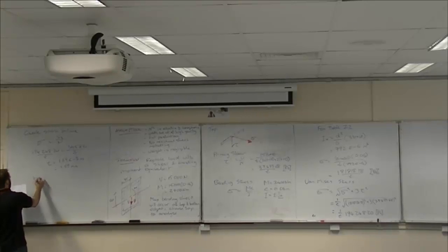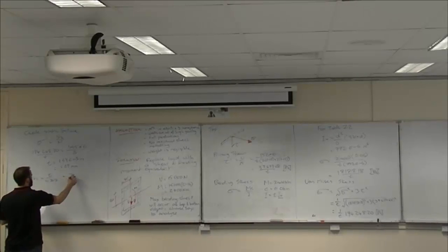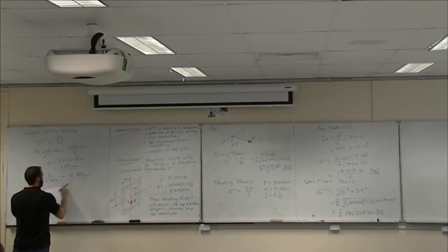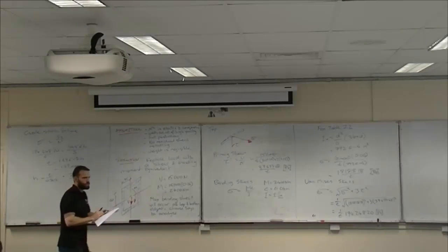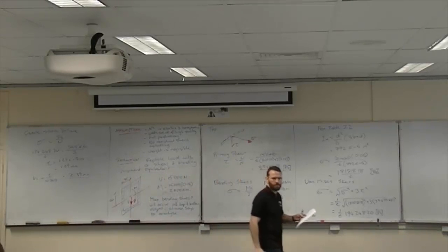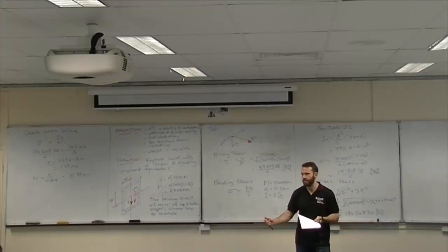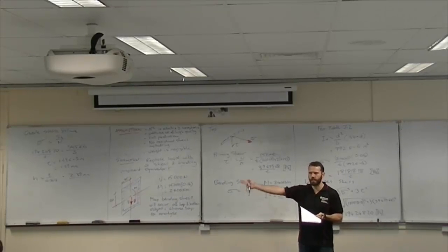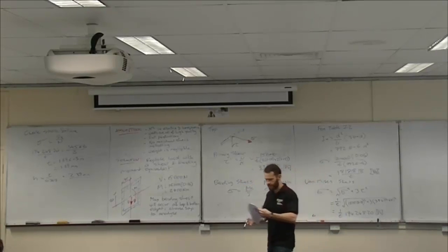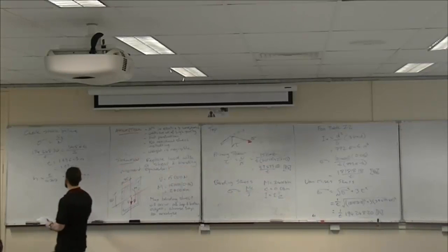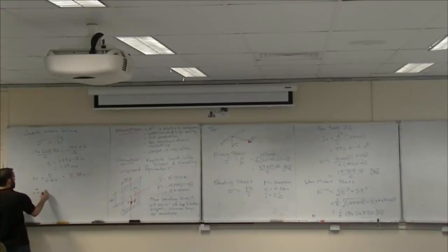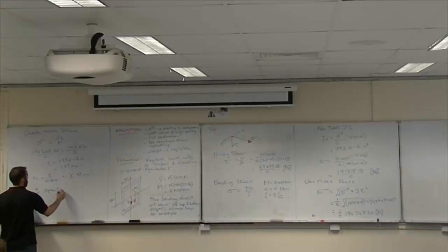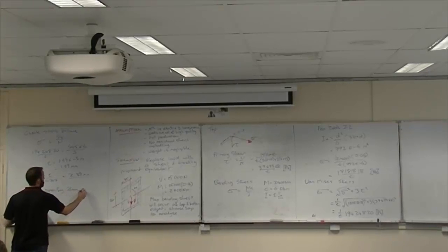So, H equals T on 0.707 equals 2.39 millimeters. Does everyone remember what I said yesterday about what we do with millimeters in terms of welds? Firstly, we round them up to the nearest millimetre, so that gets us 3 millimetres. And then, if it's less than 3 millimetres, we round up to 3 millimetres. But we're there already. So at the end, we'd say, therefore, specify 3 millimetre welds.